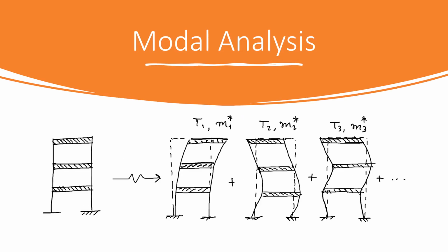Linear analysis methods have a lot of advantages. The simplifications, as we all know from structural dynamics, are many. We can, for instance, use the modal decomposition, which allows us to represent the motion of the structures using the superposition of different modes that can be activated in the response of complex structures.